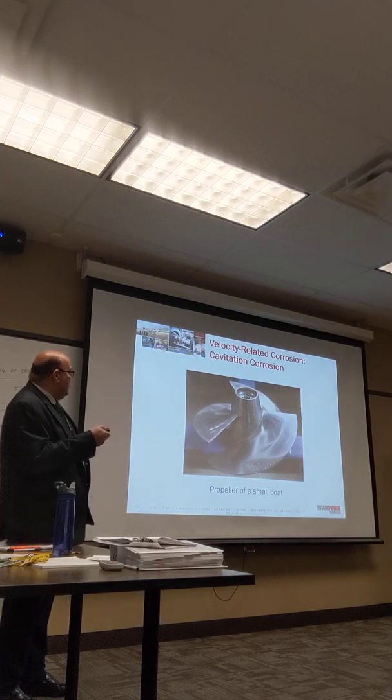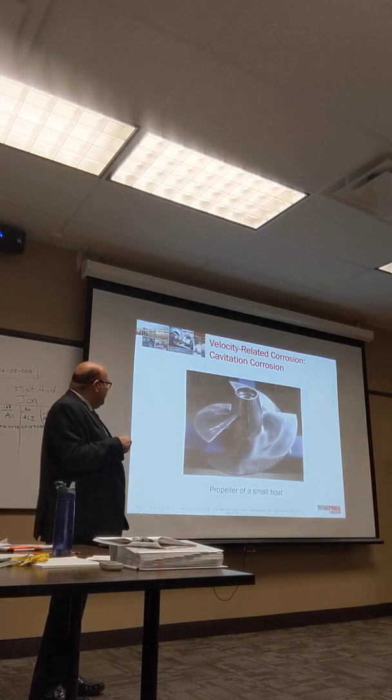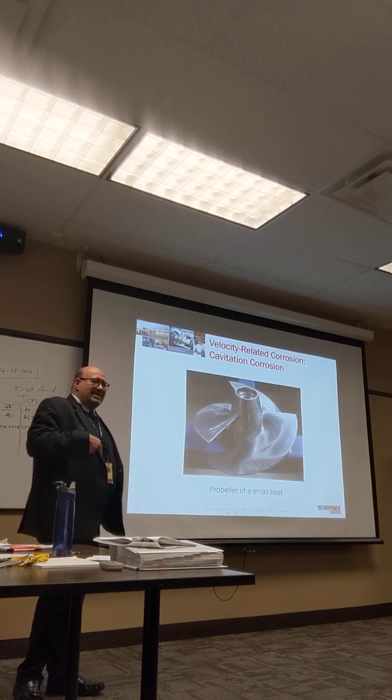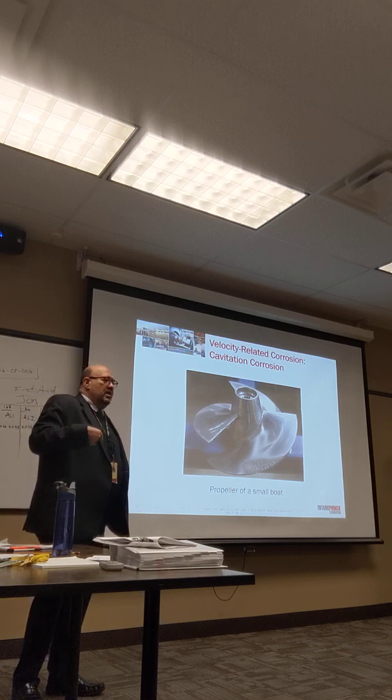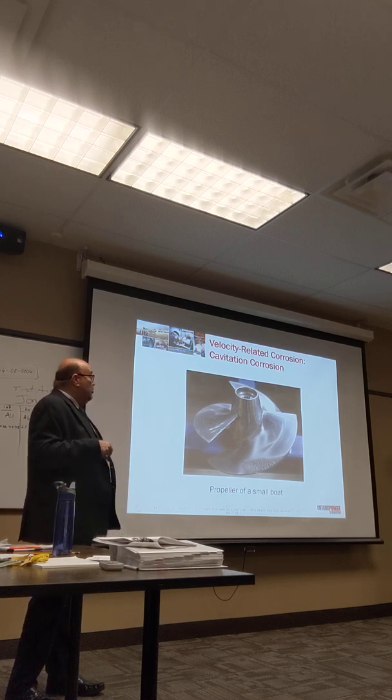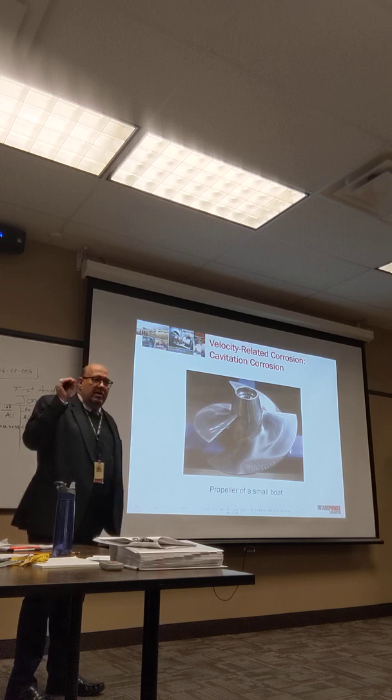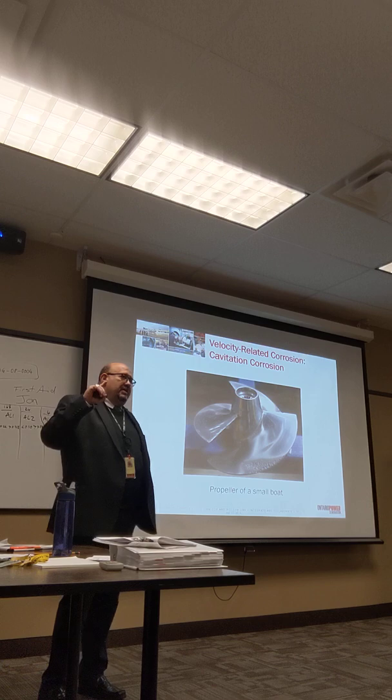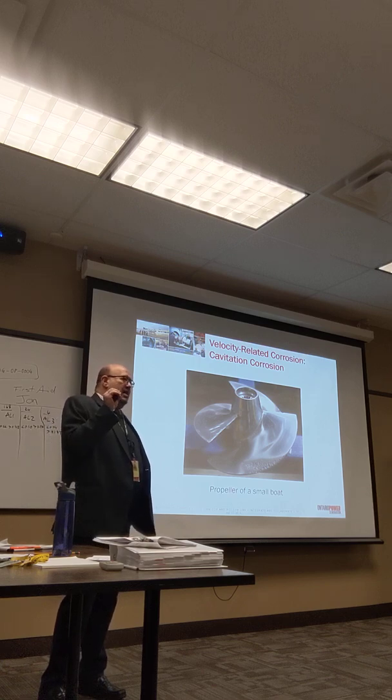Actually, I had some pictures. That's a very good picture. If you look at it here, you're losing surface, and this loss of surface roughness is not good. It adds a lot more resistance, so it actually reduces the efficiency of this blade here. As you can see, because of the formation of very localized gas pressure for the liquid, it's reached because the pressure decreases a lot, and that's